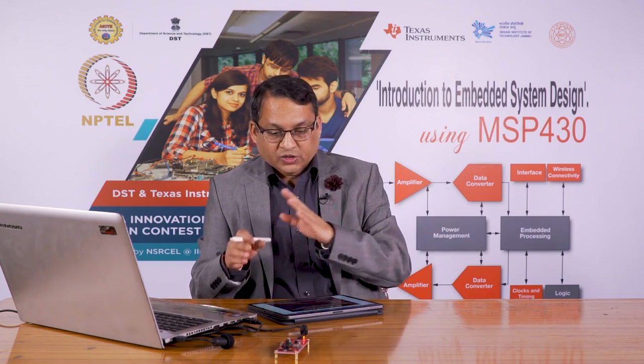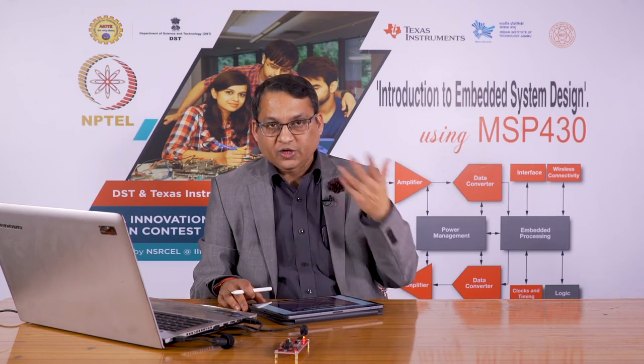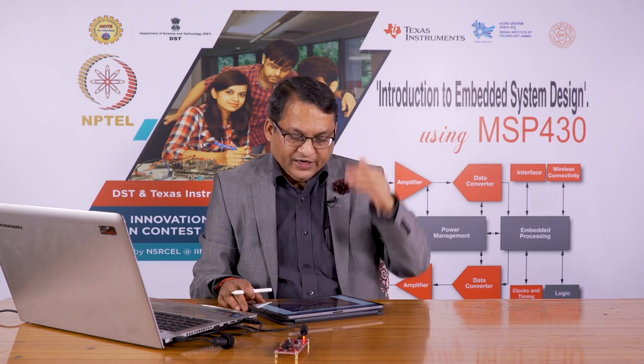Only when you want to invoke the additional, secondary functionality do you have to worry about writing into the PxSEL and PxSEL2 registers. Now, since in this first exercise we are going to deal with writing values, converting these pins to output and writing values of ones and zeros, our program is going to be very simple, but we still need to go through how we manipulate bits so that I can make a 1 or 0.